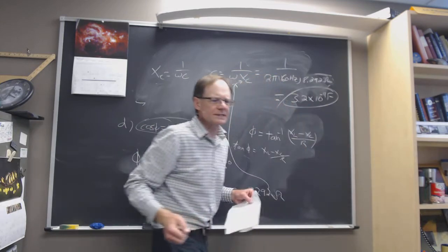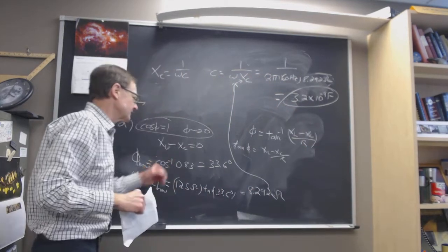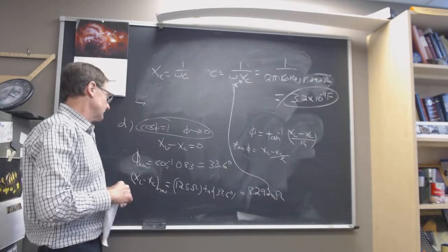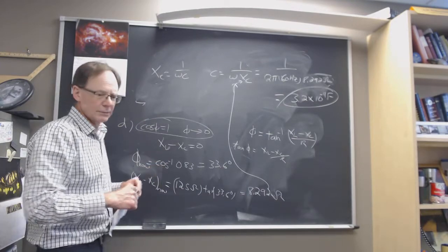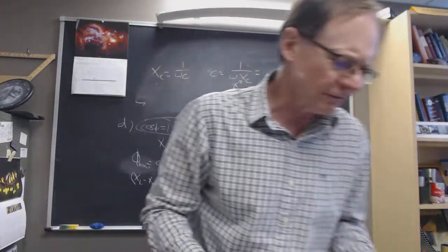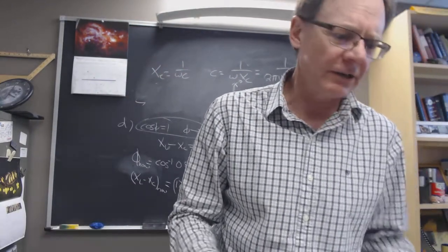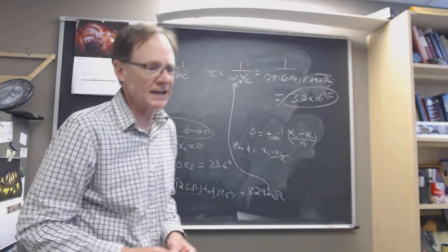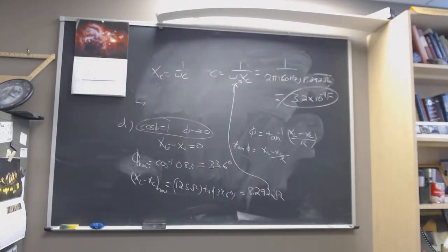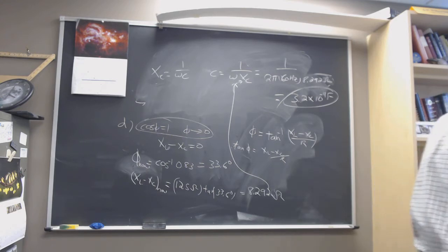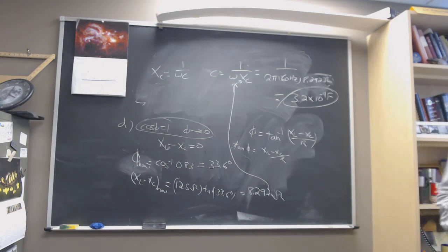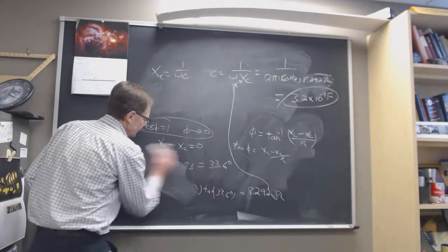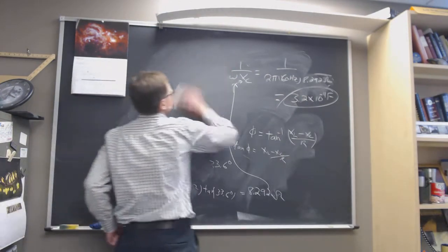That's the extra capacitance that has to be added to this circuit to turn this phi to 0, which is basically what they were asking for, to say the power factor has to go to 1. So that's problem 67. Probably we should stop this and restart it for the other problem, but I'm not going to do that. I'm just going to plow ahead and see what we can do with 68A.